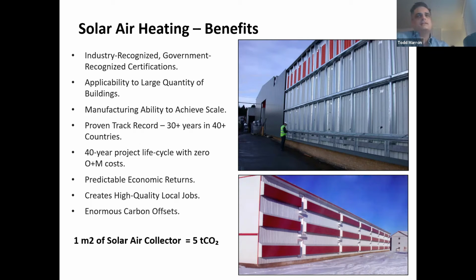As far as maintenance on the system, none. We're hitching a free ride on that existing ventilation system. There are some instances where we'd introduce new fans, like Andrew had mentioned, sometimes to make up static, even though 3/8 of an inch is usually fine for almost every system. But if you have a super long duct run or something, it might require that. Also, for example, we do a lot of airplane hangars and these types of big buildings for military, where often we'll just use a standalone fan to bring the air in as opposed to integrating with a mechanical system.